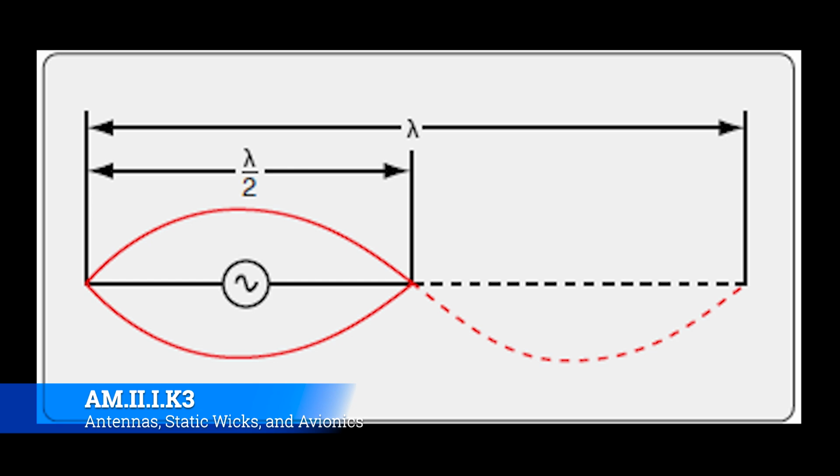Now, if you have too much antenna out there, it will actually work against you rather than for you. But if you don't have enough, you don't maximize the amount of energy that is in that AC wave to transmit. The graphic that you're looking at basically says this exact thing. It says, hey, if you take the entire wavelength and divide that by 2, that will give you the optimized antenna length for a set channel.